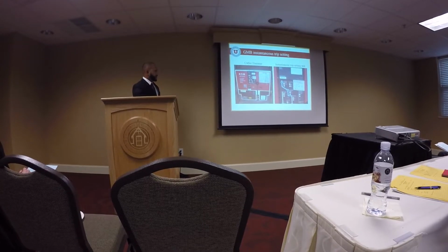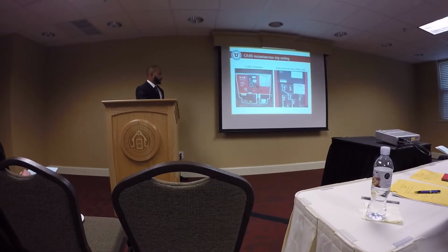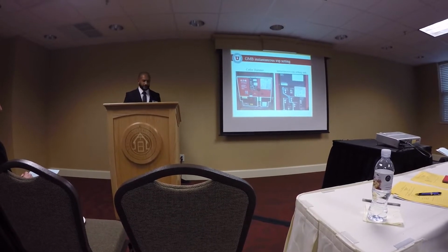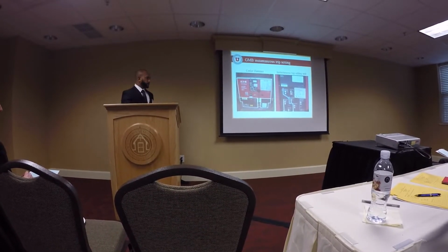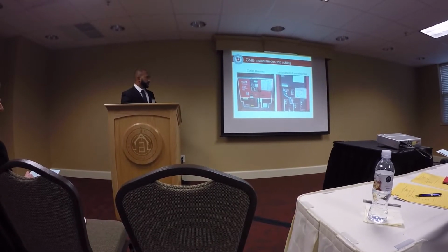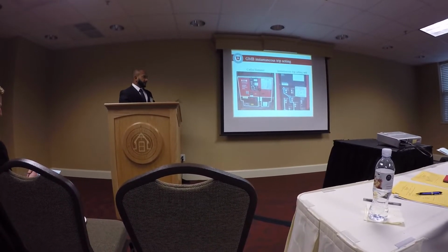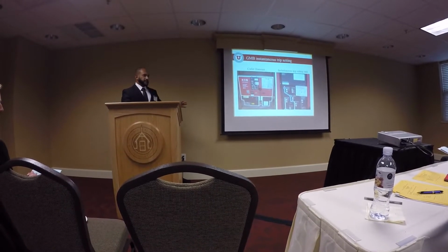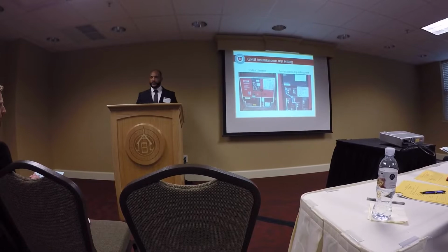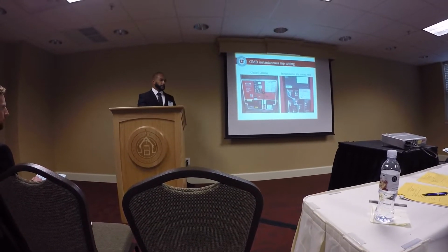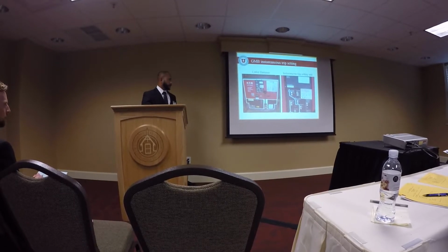So this here is the TCC curve setting. You can manually dial it, or in our case, you can program the computer, plug it in, and flash the existing TCC curve to the new one. Then the generator main breaker knows that it initially takes 6 times the current to start up the generator. Once it starts up, all you need is 1.5 times to safely operate.